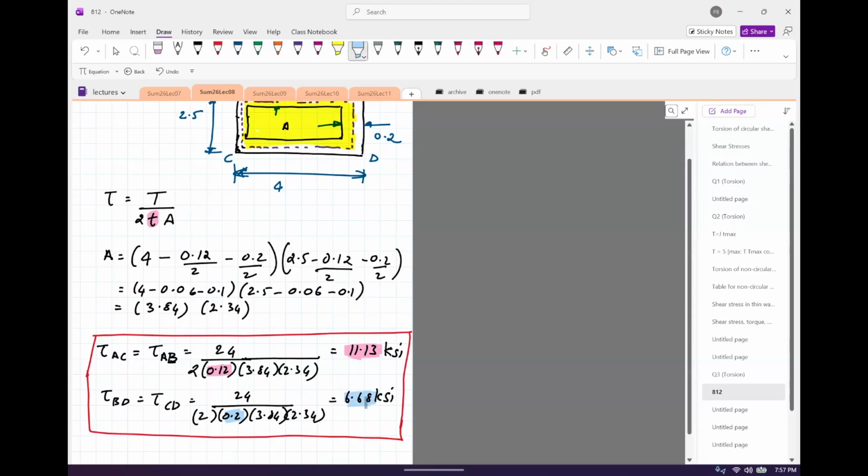And this correlates with everything we've seen in the class. The bigger the shaft diameter, the larger the area over which the force can redistribute, and you'll have less stress. So you always want to have a big thickness to have less stress. The consequence of this is that you need more material. More material usually means more cost, and it's going to be more expensive.